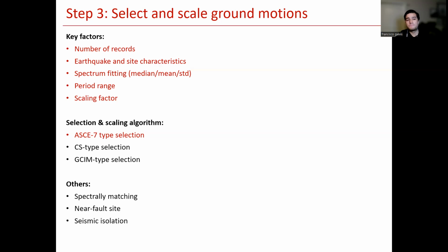Then how would you plan to fit the ground motion spectrum with the target spectrum? Are you planning to fit the median, the mean? Do you care about the standard deviation? And then in what period range? And then finally, what's the scale factor that you feel comfortable with?